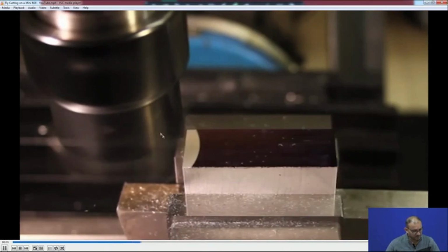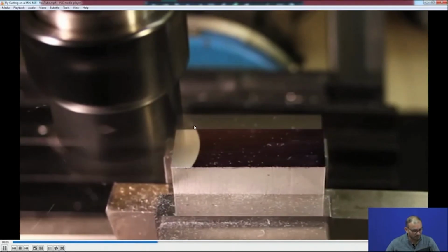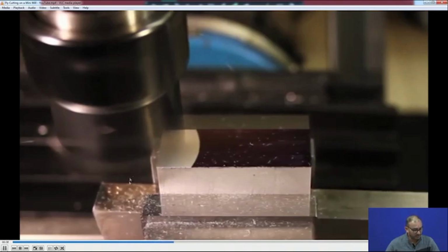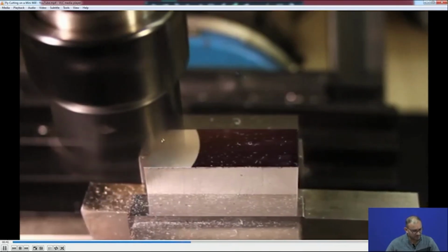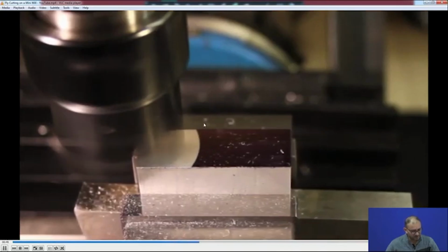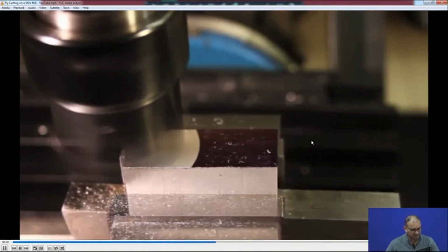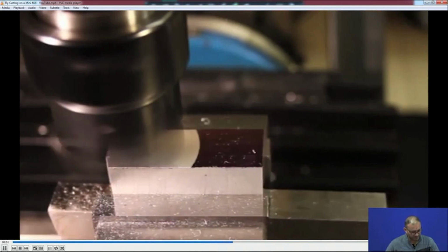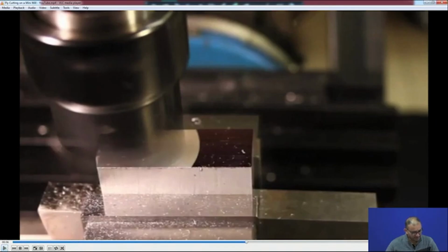So, what is the advantage of this thing, that here what happens, that you can actually do material removal on a very large surface, depending on what is the working area of this particular fly cutting tool. If it is larger, that means you can get even tens of centimeter of workpiece cut in a single pass. No need to do a multiple pass for machining of those components.